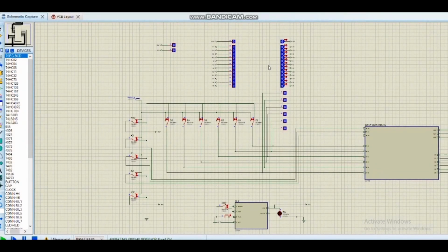To actually run our SAP, we have some opcodes from our manual. So we know that load is 000, add is 001, subtract is 010, output is 011, and halt is 111. To run this computer, we first have to give the proper instruction data in the particular RAM address.